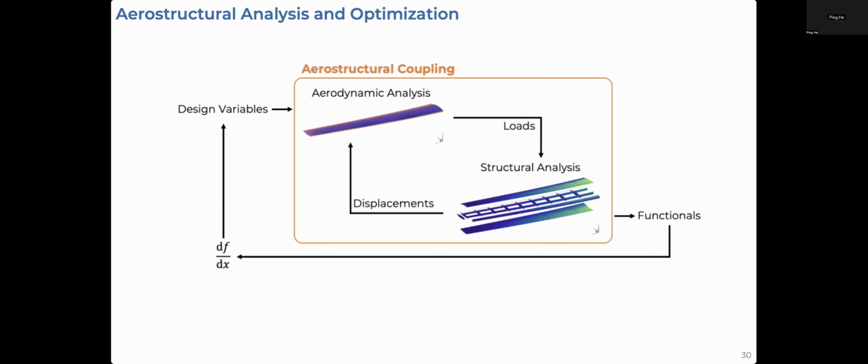The methods that we use are RANS-CFD with DAFoam for the aerodynamic model. We have a load and displacement transfer tool that handles these loads and displacements between the aerodynamic and structural models, and then we use a finite element analysis tool for the structure called TACS.